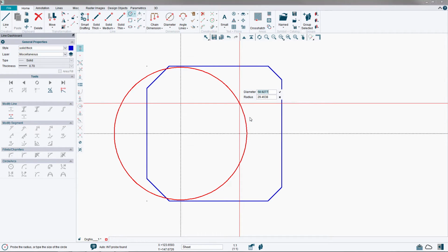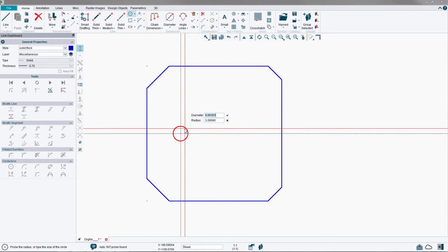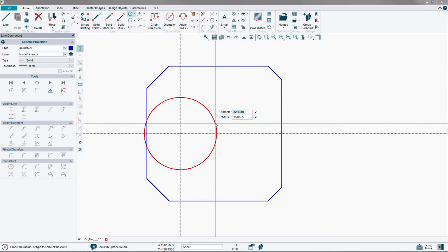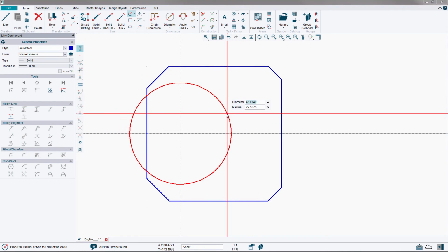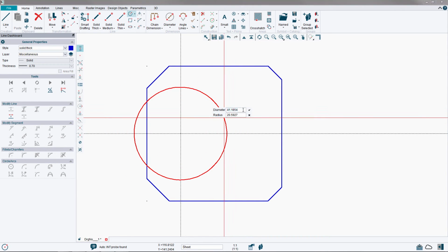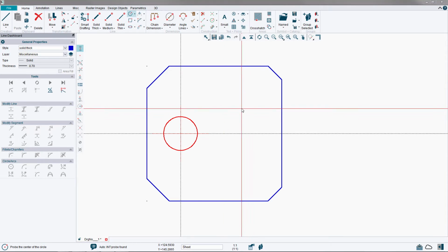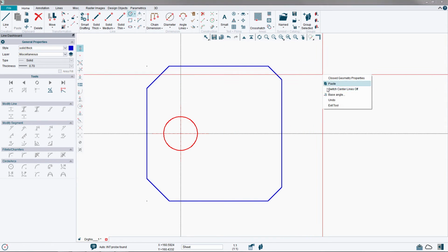We can create the circle using a second left mouse button probe or use the input menu to give a diameter. Using the Control key, we can create the input value of 16 and press the Commit button. The circle is created including the center lines.